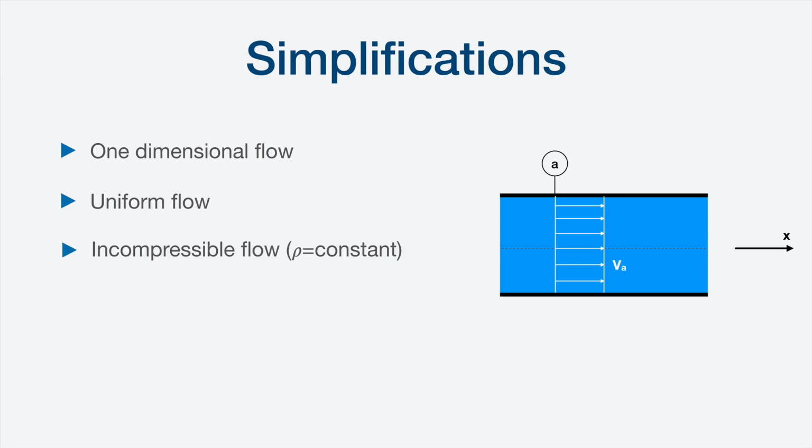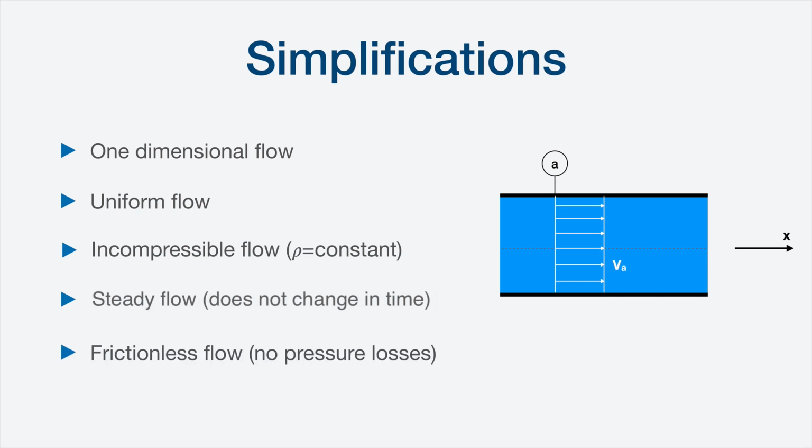The flow is incompressible. We know that liquids are almost incompressible. We can make this simplification because the fluids pumped by pumps are liquids, so that's okay. The other one, the flow is steady, it doesn't change with time. What we do is to study the movement of the fluid at each instant of time. So we will always consider that the flow is steady for our application, I insist.